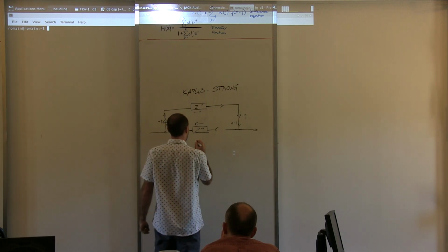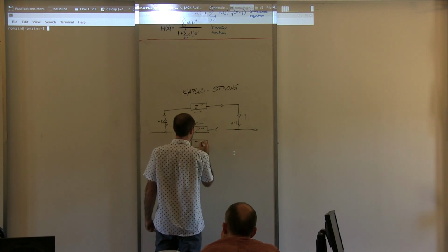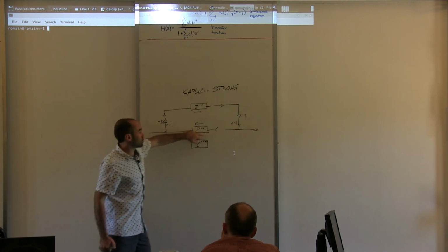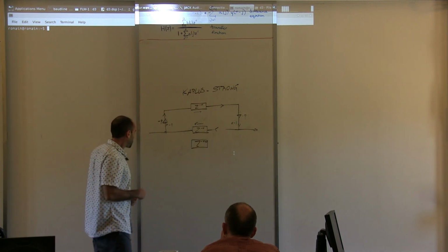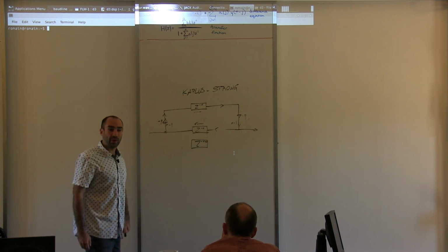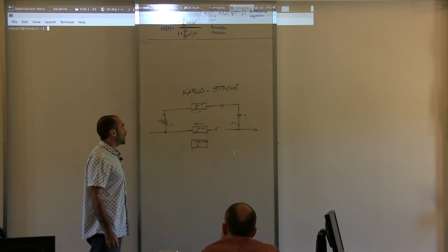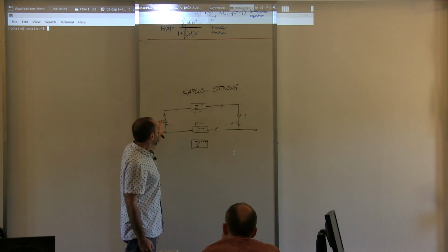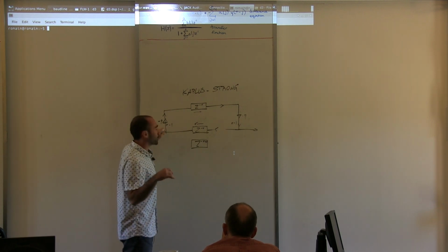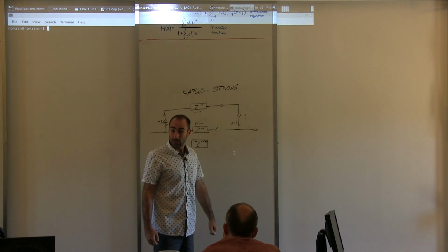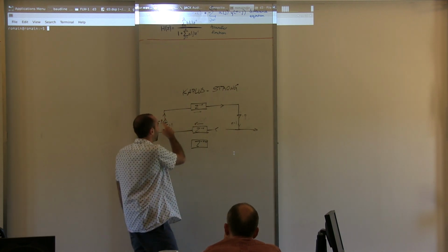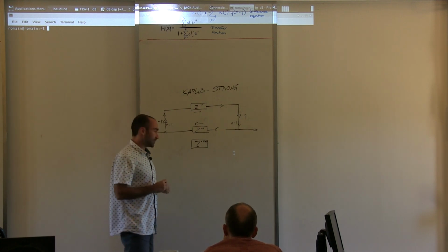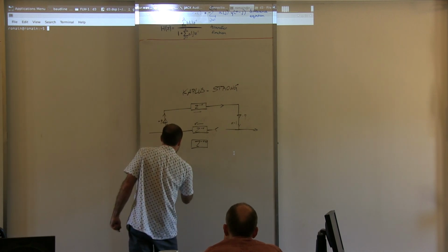So then I can just have one delay line that is basically z to the minus (n plus n), and then we have the right amount of delay in the entire loop. And what about the multiplies that we have here for the reflection? In the case of the Karplus-Strong algorithm, we only have one multiply. Because now there is virtually no proper termination, and there is a sign inversion every time, we remove the sign inversion. It's like multiplying that guy by that guy here. Now, instead of a sign inversion, we have a positive coefficient. So the Karplus-Strong algorithm is basically going to look like that.